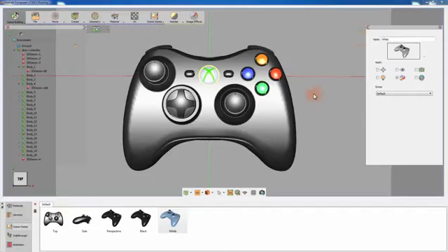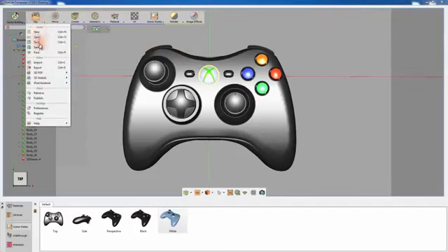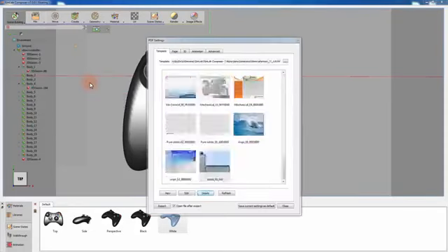Once you're satisfied with the scene states that you've created, you can proceed to the creation of the PDF document. Click on the File menu and go to 3D PDF, where you can export a PDF document, modify the PDF settings, merge several PDF files, or embed the PDF document in a web page. Click on the PDF settings.